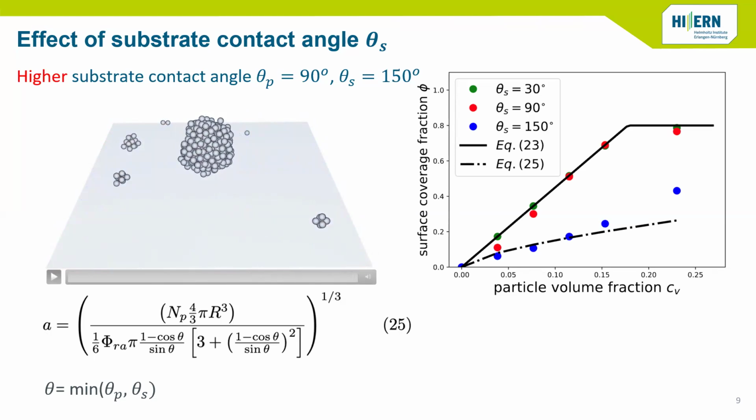So in the initial phase, we just assume that after dewetting a single spherical suspension droplet formed on the substrate. And then we also know the point of dewetting is when the contact line is pinned on the particles. So that's why we know the total volume of the solution before dewetting. We can calculate the radius of this droplet. And the droplet will also keep drying in a constant angle mode.